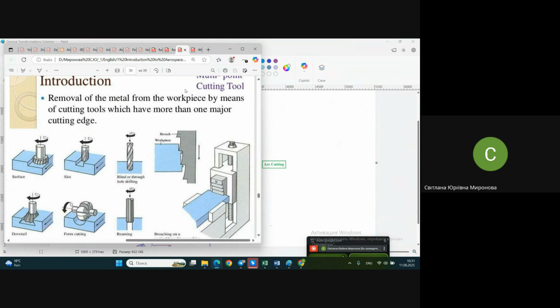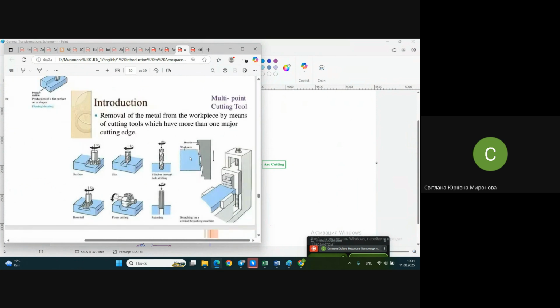Once you pass this broach through the material, with one linear motion, you have already passed it with 20 different tools, for instance, if you have 20 blades. So it's a very effective process in terms of time spent, but you understand it also has limitations.